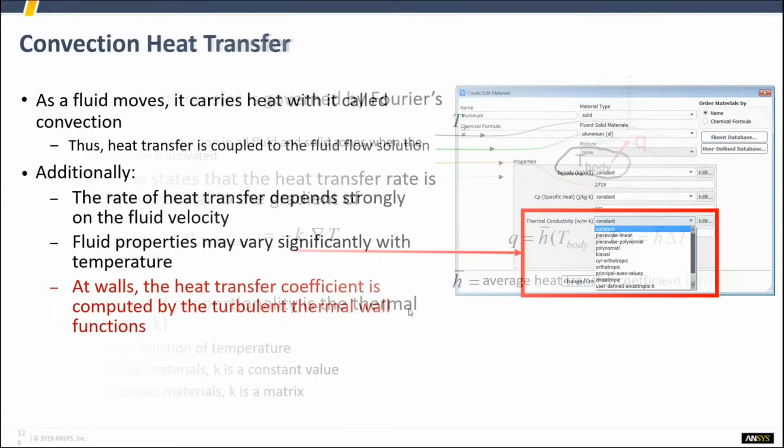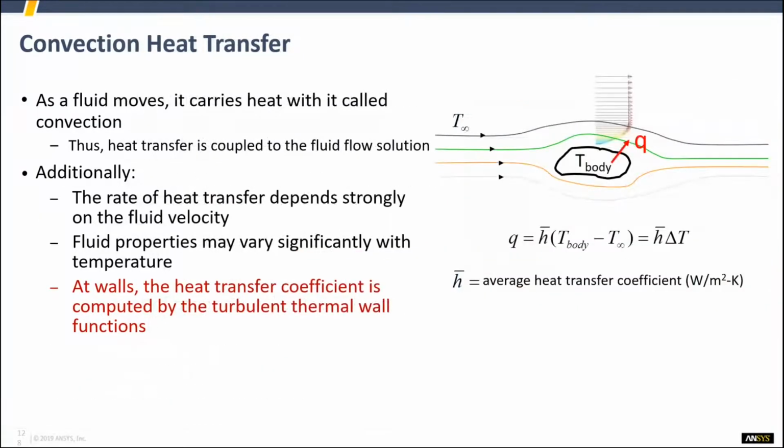The next method of heat transfer is convection. Okay, and CFD is the best way to pick up convection, right? Because generally what you do in FEA or other analytical methods of understanding heat transfer, you have some coefficient that you've assumed based on either testing or some assumptions that you've made, and that H value is really important.